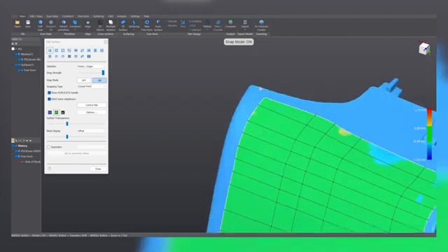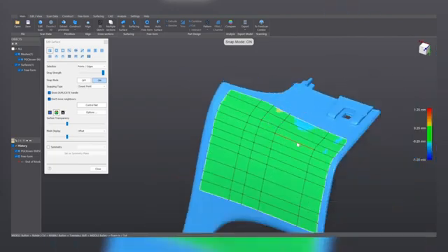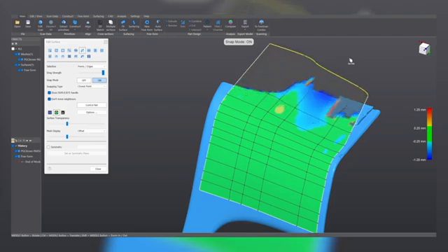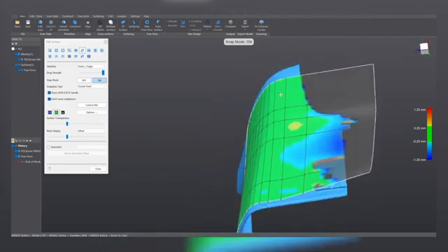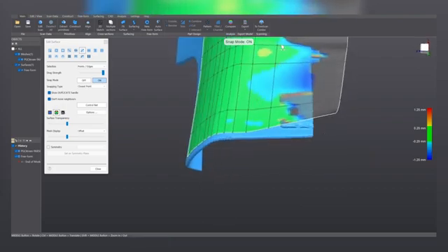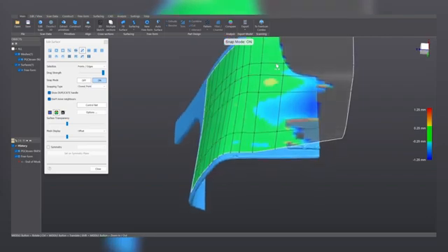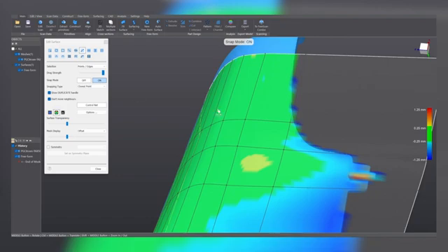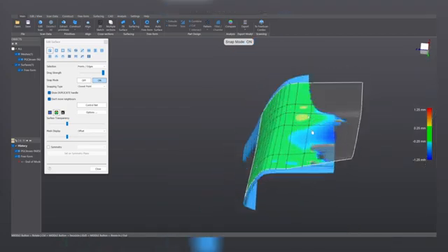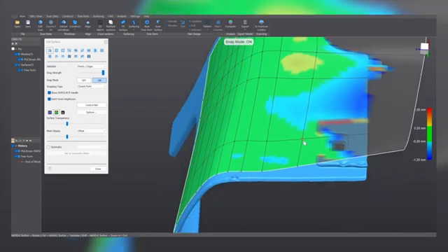And now, instead of extruding more and more and more faces, we are going to extrapolate the current surface that we have. So we click on here and we select the edge and we extrapolate it. Okay, now we have points, vertices of this surface that are onto the mesh and points that are not onto the mesh. So let's first take care of the points that are onto the mesh. We go to the manipulate, and with the snap mode on, we move them a little bit and let them snap onto the mesh to give us a surface that adjusts well to the mesh.